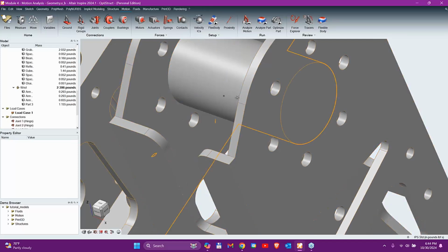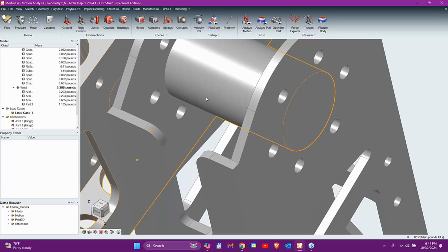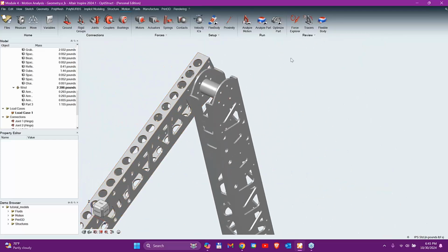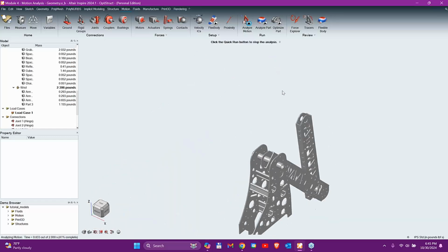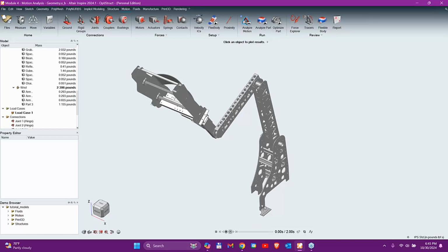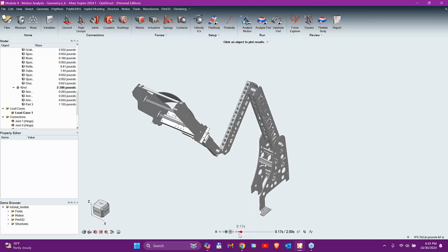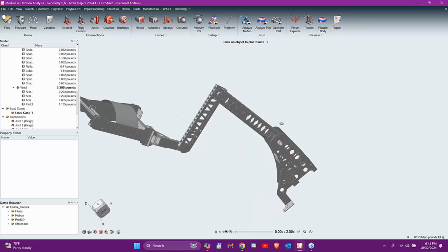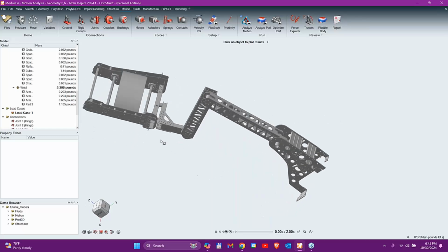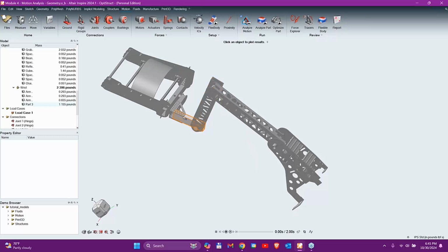I'd probably click the wrong thing, but that's fine. That one hinge will actually work. And now if I come here and look at analyze my motion, you'll see now we get a real wild design because I got two things connected to each other, and I progress through and I continue that through each one of the different joints that I have, combine things together.